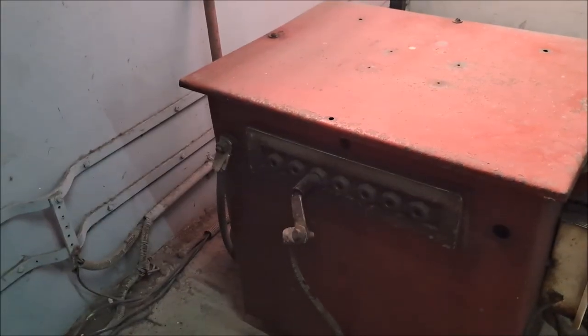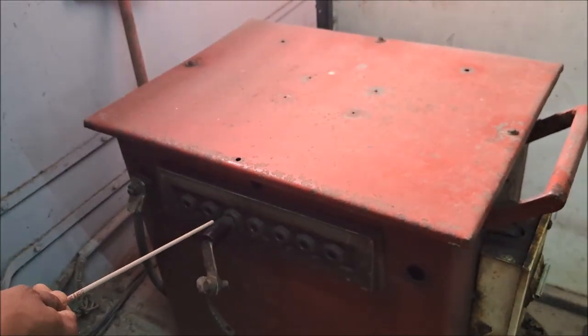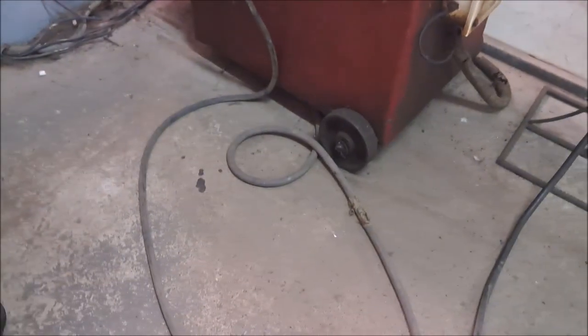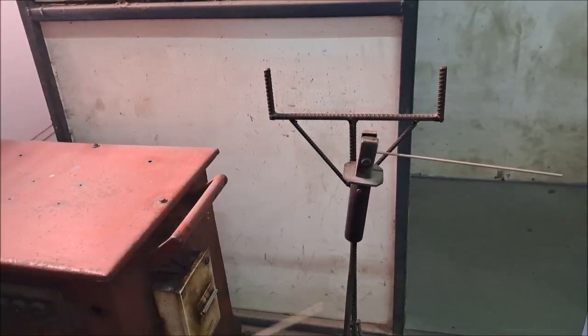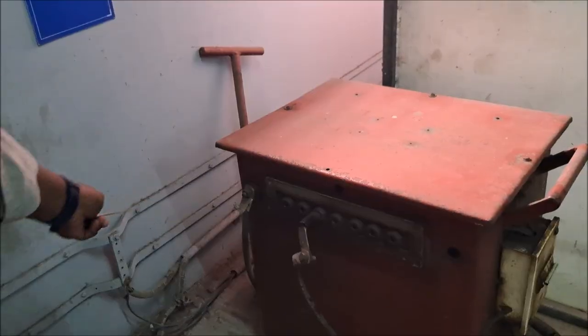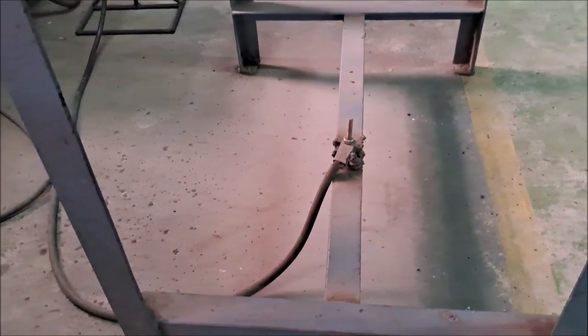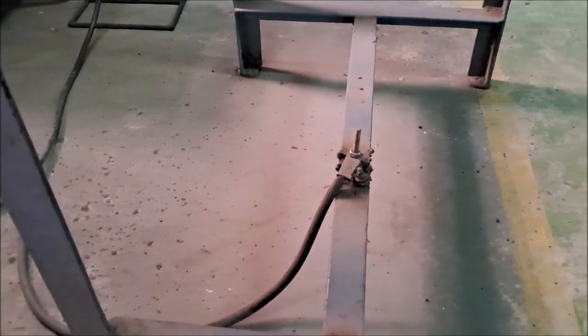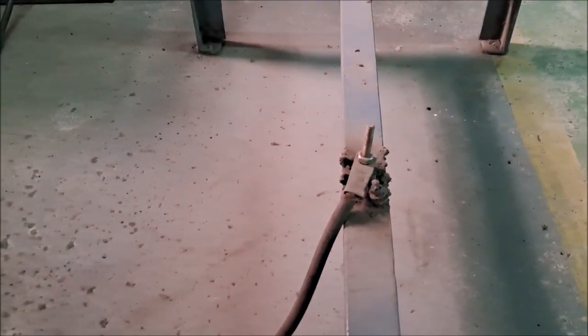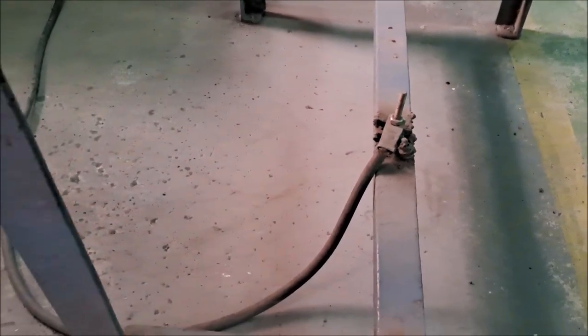Here two types of cable are there. One is the welding cable, connected with 150 amps like this. One end is connected to the machine and the other end to the holder. The other cable is the earth cable. One end is connected to the other terminal of the machine and the other end to the working table. Only when you connect the earth cable is welding possible. Otherwise, continuous welding is not possible. The earth cable is the main thing.